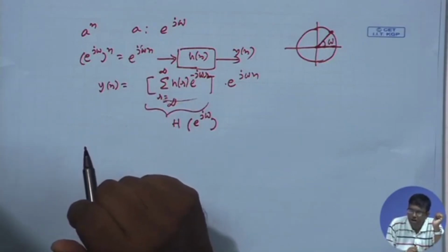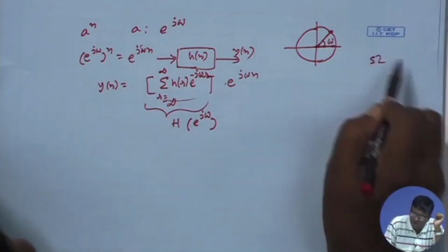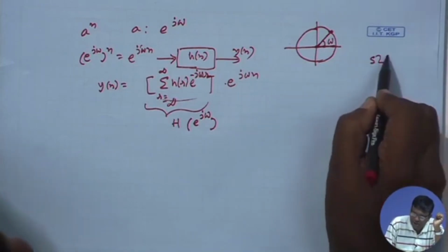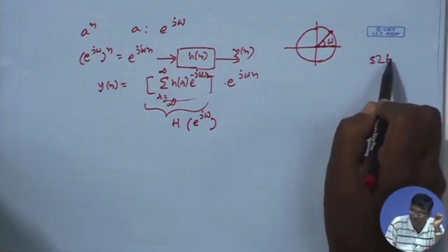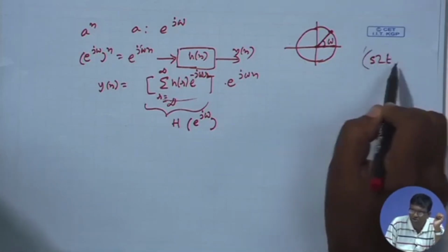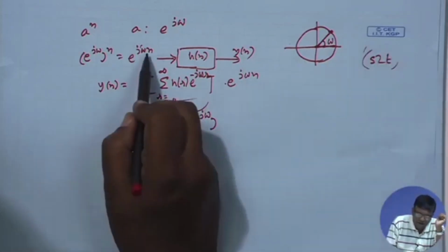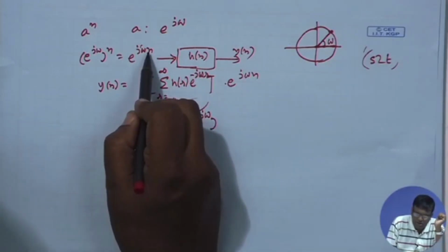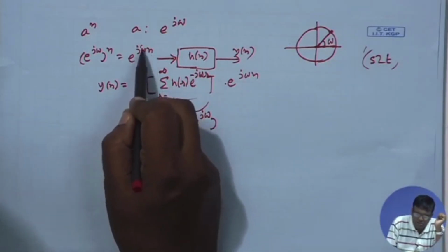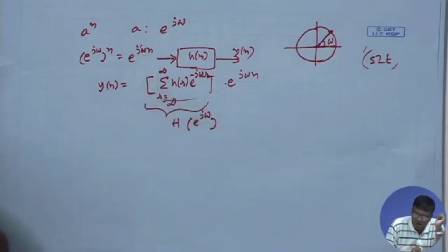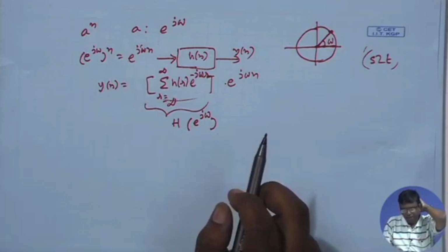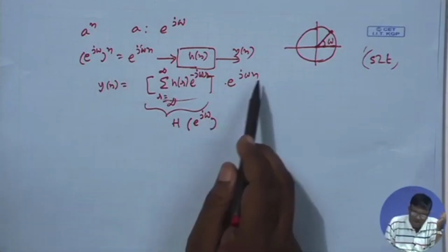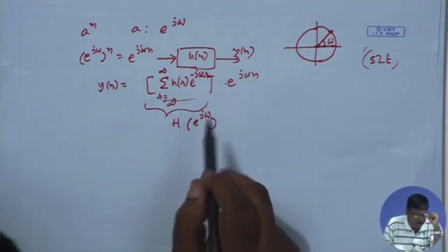Analog frequency, radian per second, we denote it by capital omega, radian per second, because omega into t comes, and t has a unit second. So omega per second into second, the seconds cancel, and the whole thing becomes an angle, radian. Here n has no dimension, no unit, it is dimensionless, that is why small omega must be radian only. So the product is radian. This omega is called digital frequency. Fine, so there is nothing new that has come up so far.